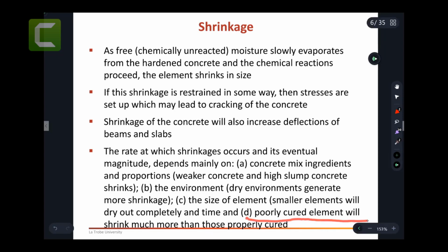This is to do with the builder and how they're going to manage to cure the concrete on site. You need to understand if it was poorly cured, like not enough, if it was very, very warm weather, like 40 degrees in summer. Usually builders and building practitioners know that when they pour in concrete, they have to make sure they either carefully apply curing and watering mechanisms or processes, or they will ask the supplier to add mixtures, some chemical materials, to make sure the water is gonna stay in the mix and slowly get evaporated.